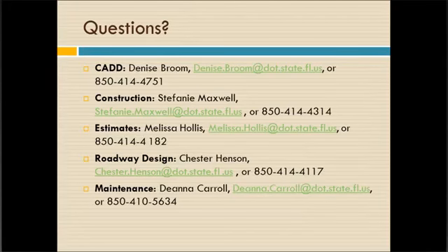If our project is past constructability, we have yet to calculate quantities. Should we use the new pay items? That depends. When is it to be let? I'm assuming, but I hate that word, that if you're just now getting past constructability, you haven't made it to 90s, it's going to be after July of 2015, in which case you definitely need to use these new pay items. Because the pay item is changed, if you've already drawn everything in CAD, you'll just need to go back and select those and set them using the new items in the DNC, and you should be good to go.